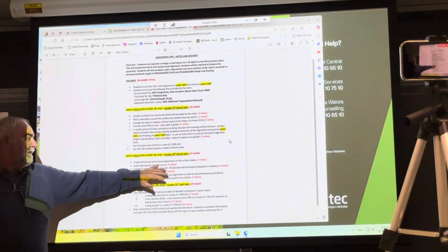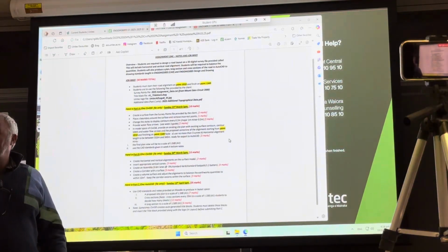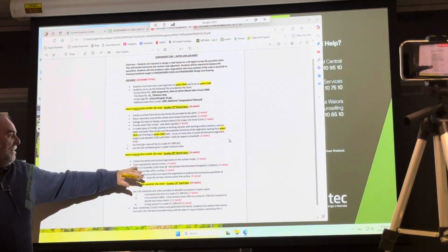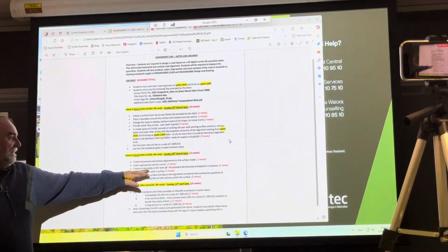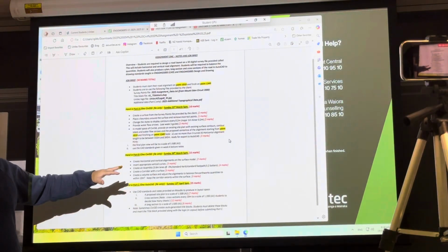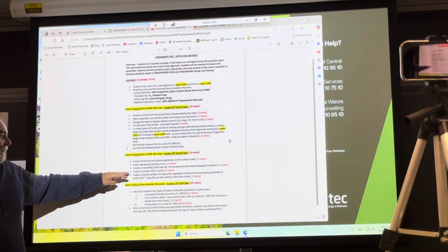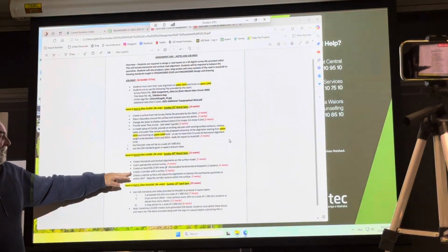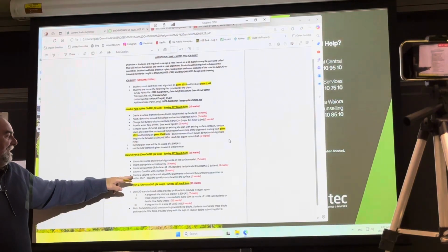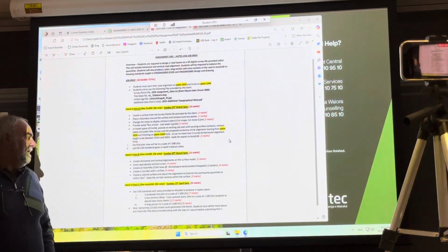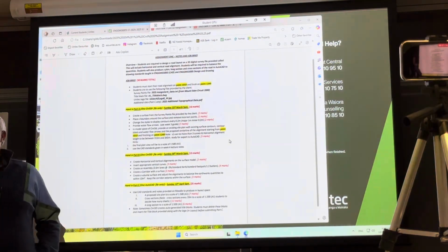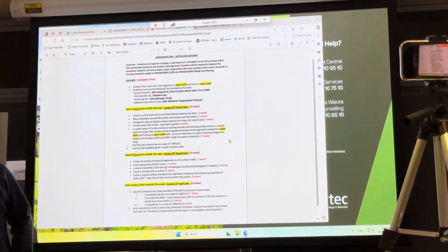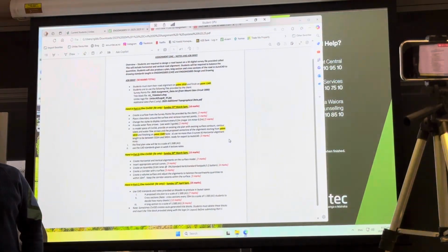When you start doing your horizontal and vertical alignments, that's when we're going to do the long section. And you're going to be putting in some vertical curves, creating an assembly slightly different to what you did. So I'm just going to make you work a little bit harder to find those. Create a corridor. And your volume, you're going to keep adjusting it. If you want those 3 marks, you're going to keep adjusting it till it's under 10 cubic metres. You don't just pump out that volume and hope that I give you something for it, okay?